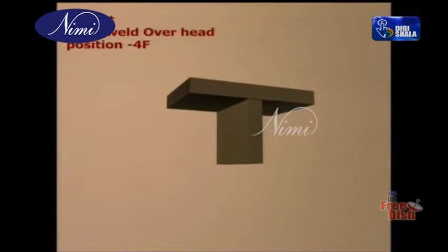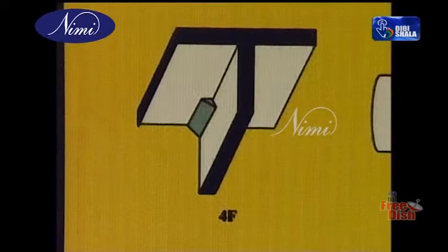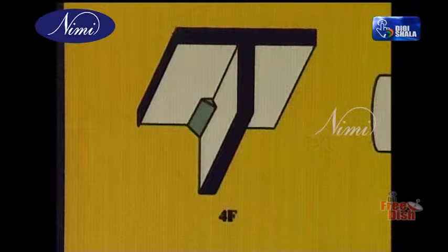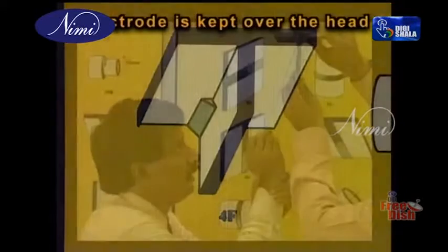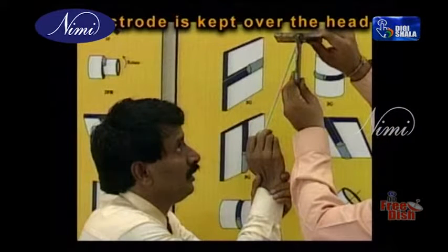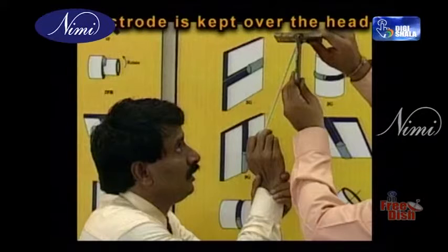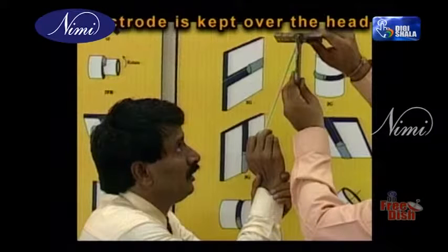4F overhead position. In most projects, the welder may weld something above and the weld metal comes against the gravity. The electrode is kept over the head like this, and the welder tries to do this electrode manipulation. This is called 4F welding.